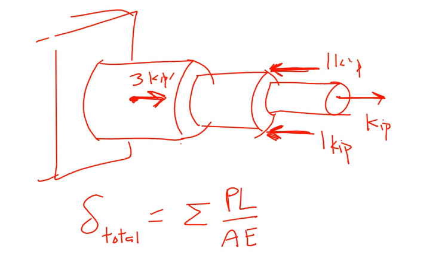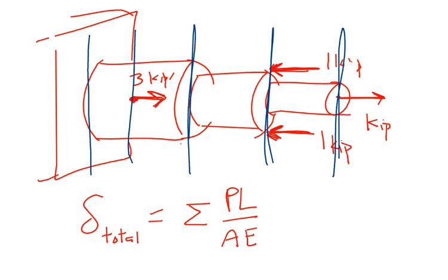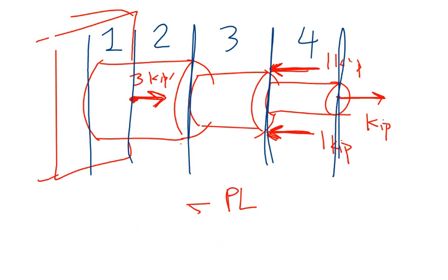Okay, so let's go ahead and determine the internal forces in our segments. So what I want you to do is this. You're going to specify each of your segments, right? So I'm just going to do this. Okay, this is segment 1, this is segment 2, this is segment 3, that's segment 4. And our next step is to find the internal force in every one of these segments. So here's what you're going to do. Remember, this is first and foremost a statics problem. So I have to find a reaction at the left-hand side.